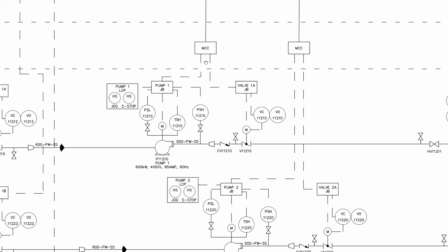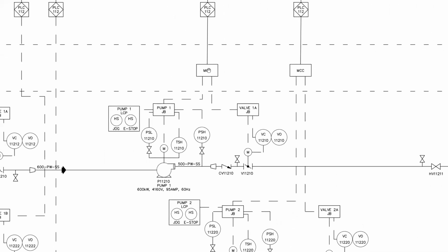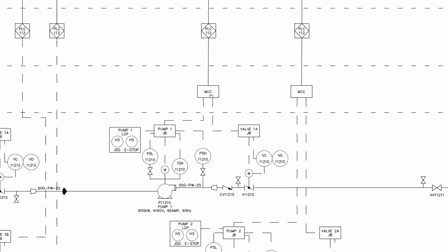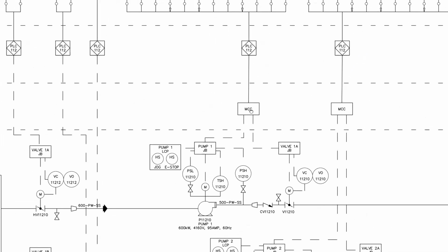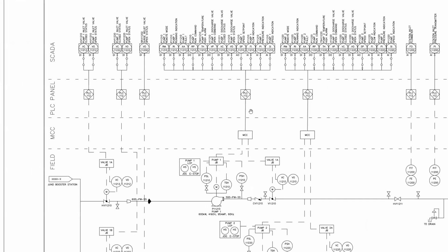These then feed up to the MCC. So inside the motor control center, which I showed you guys a photo of. Does everybody know what I mean by motor control center? You might not know what I mean. It's going to be where the VFD may live, the main motor circuitry, high voltage, higher voltage, technically medium voltage stuff.